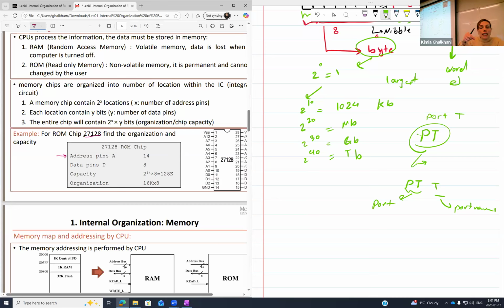Otherwise, I was using a console for such a simulation. I was running the design, and then I had to leave it a week or two, and still it wasn't done. After waiting for such a long time, I would receive an error. Why was that? Because when you mesh, you guys already learned about CAD design, so you know what a mesh is. When you create an object inside a 3D design, you have to mesh it, meaning you have to define how accurate you want the calculation to be, especially when looking at finite element analysis.